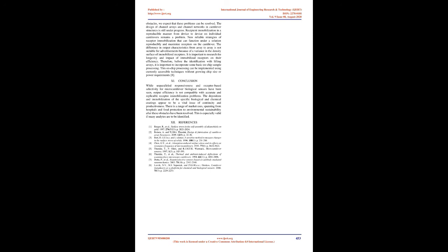In the upper section, a titanium cap is shown on the left side of the closed capsule as the circular membrane. A membrane filter to partly isolate the analyzer from the interstitial fluid is placed below the cap. Two sets of four micro-cantilever piezoresistive sensors linked by Wheatstone bridges are used. The signals are sent to a sigma delta ADC and then to a very low power microprocessor. This is designed to modulate the transmissions to a receiver or computer where details are displayed graphically. In today's form, both chemical and body temperature can be transmitted every 5 minutes for 6 weeks by the telesensor